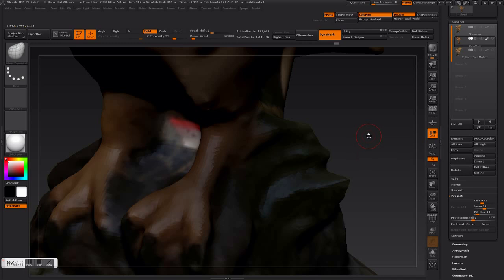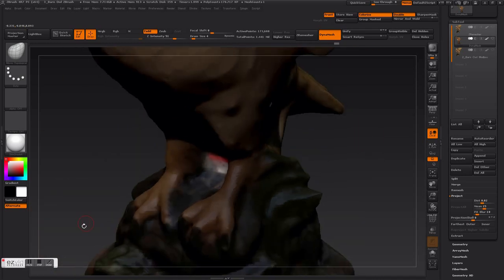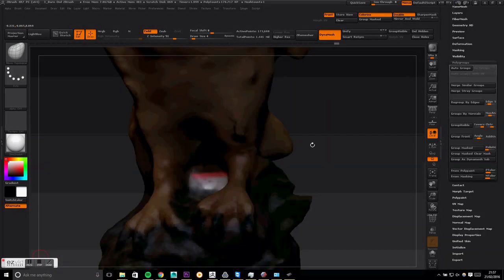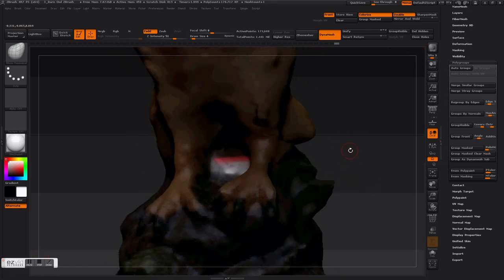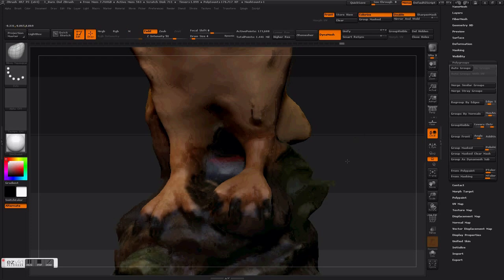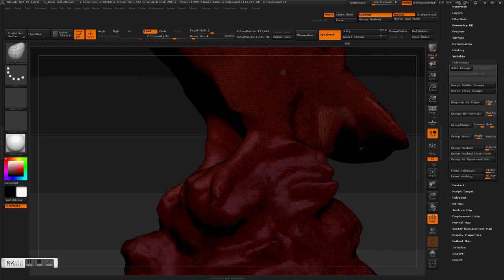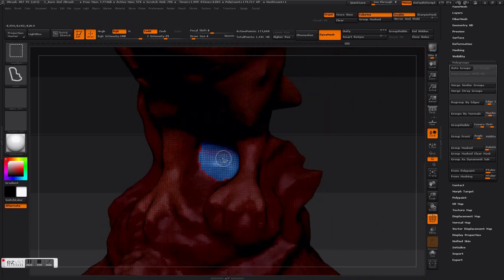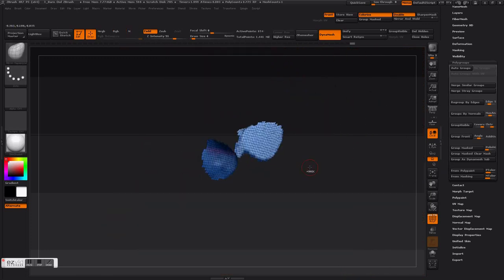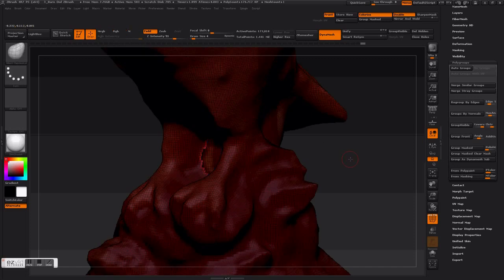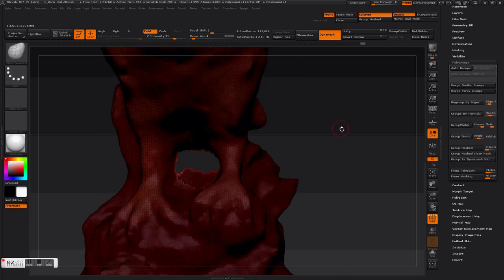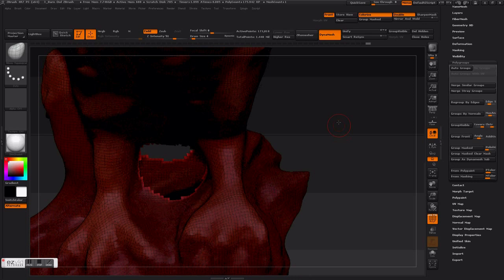This would be interesting. I'll just pause this video. Okay, so I worked out how to do it. The way to do it would be to go back to how it was with it being masked, and then you group that mask. So now these are two different groups. So now you can select the group which you don't want, and then actually select the one you do want, and then you get the hole. Then you can do what you did before and press the delete hidden button.